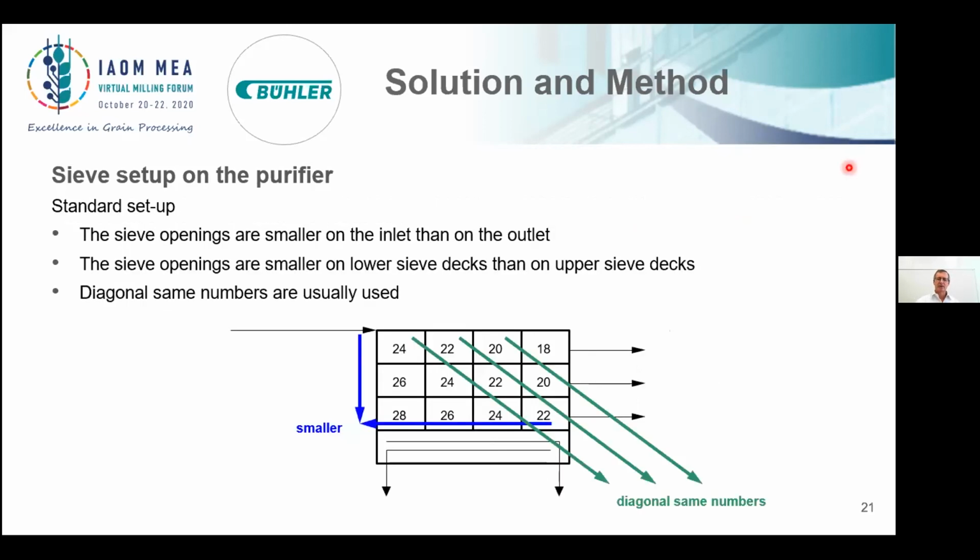How to arrange the sieves? It's a key. The biggest opening is always on the top end. So we are starting to give the semolina always a chance for the next sieve, which is more open, more open, more open, either to go through or to go over. And the air will keep the bran or the light products floating.